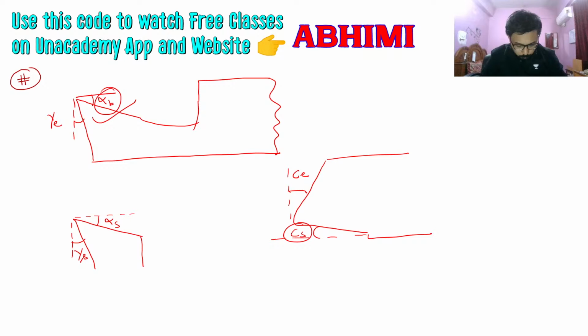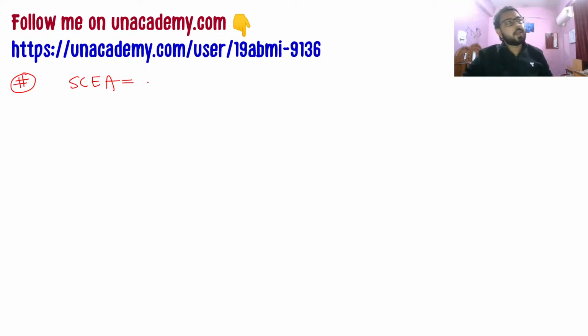Let us move forward, and I will also show you one important thing here. The value of relief angle I showed. Now let's see the value of side cutting edge angle. It will be equal to, I think, 15 to 30 degrees.